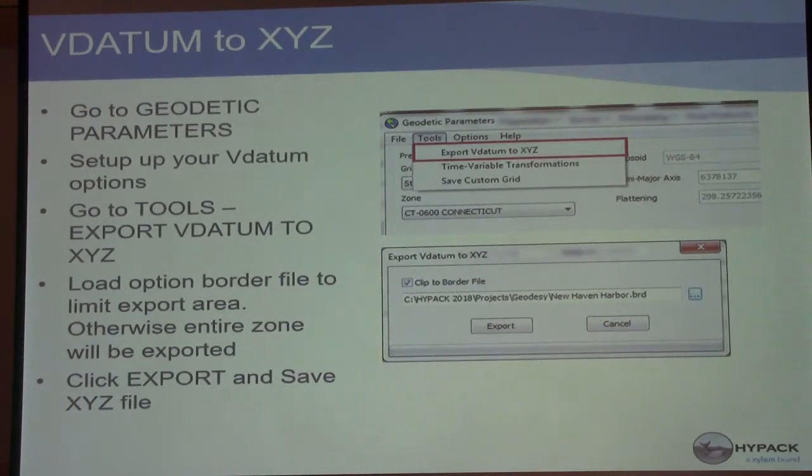I can use the fudge factor whether I'm using a Geoid with a user value or a Geoid with a KTD. Yeah, because the Geoid model just takes you down to that Geoid. You still have to get to the chart datum, you know what I mean? So you can either use a VDatum, a KTD file, or just whatever the value is. From the Geoid model to the chart datum might be 3 or 4 feet in that area, and it might change 5 miles down the river. So if it's changing and you're surveying all that area, you might want to create a KTD file. But if you're working in a small area, you just put in that one fudge factor value right there, and it's going to bring it right down to your chart datum.